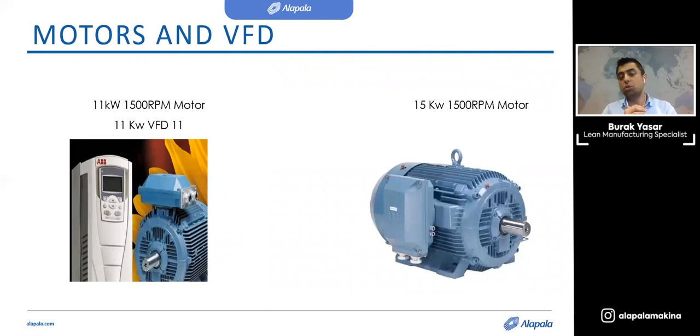Okay. We used 2 electric motors and a VFD device. One of the motors is 15 kilowatt and the other one is 11 kilowatt with an 11 kilowatt VFD device. I'm pretty sure you are asking the same question, why are these different from each other? If you remember well, one of the benefits was low thermal and mechanical stress, right? So we can reduce our fan safety factor by 20%, and of course I can use a smaller fan and motor for the same demand. Let me show you that on the technical data sheet.